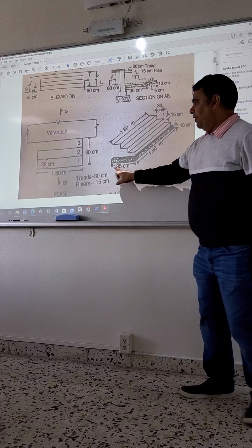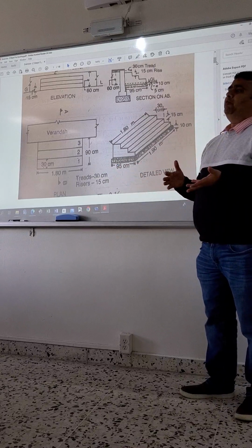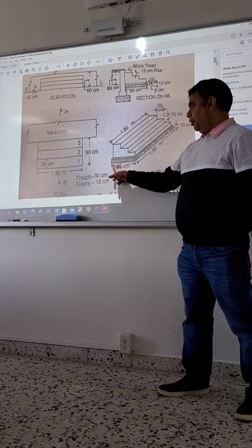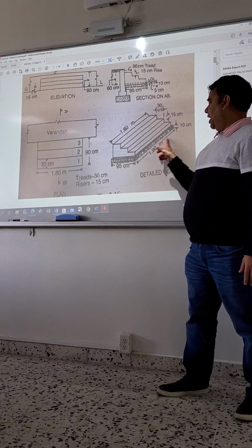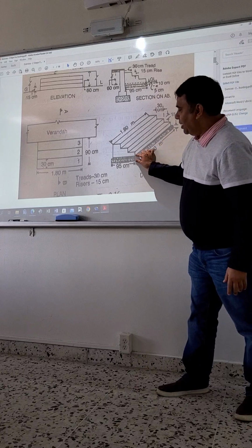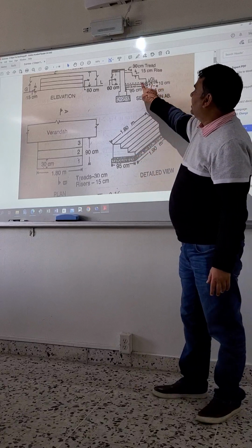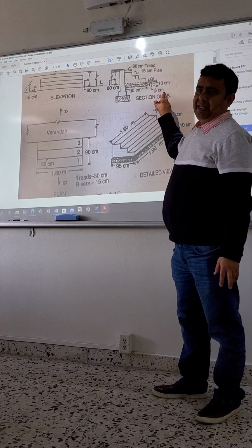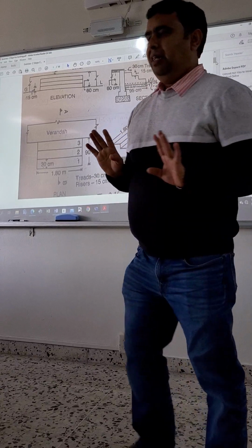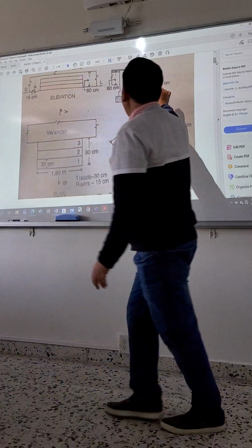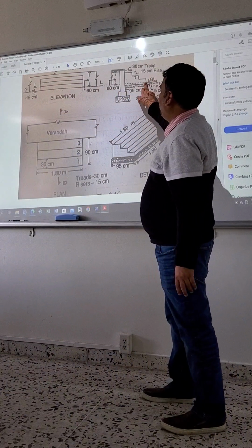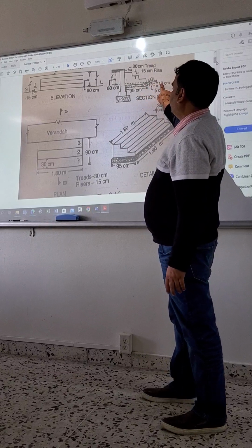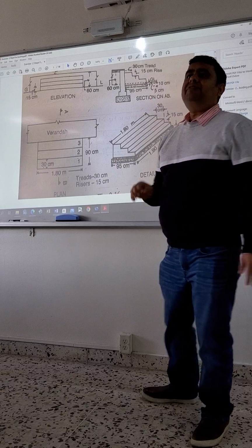Now here, so that is why here, if we want to calculate what is the earthwork we have to do, we have to excavate. So that is 0.95 multiplied by 1.9 and multiplied by this. So how will you get it here? This is the ground level. So this is 10 plus 5, 15. Got it or not? 10 for what? This is down, 10 for the PCC, and then ground level is above this. So total is 10 plus 5. So that is 15 centimeter.